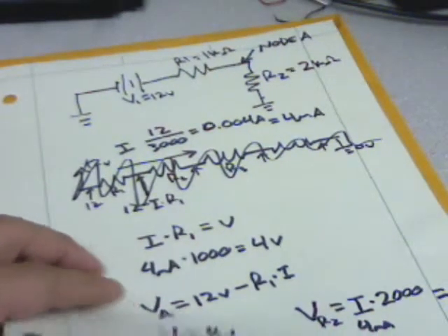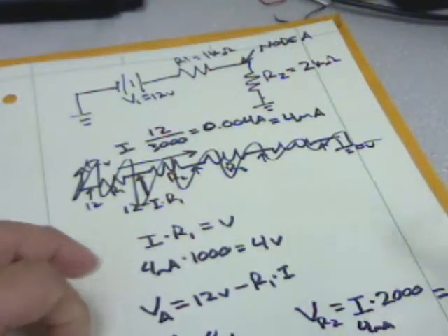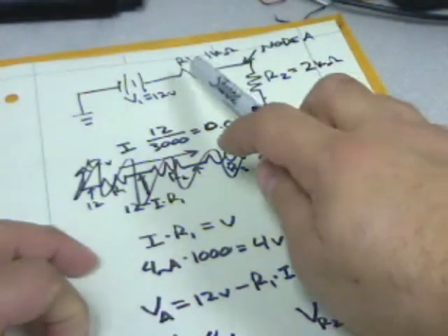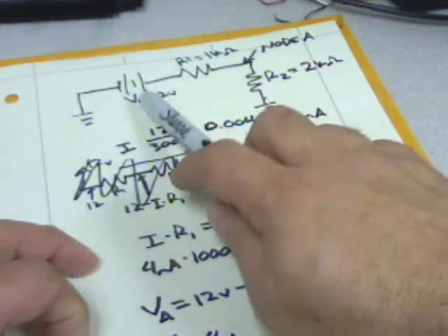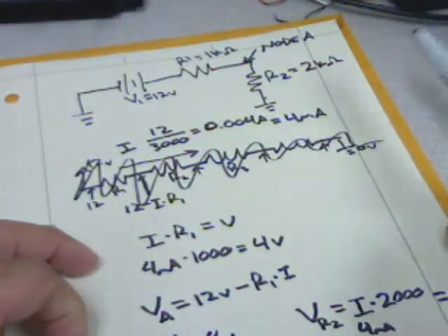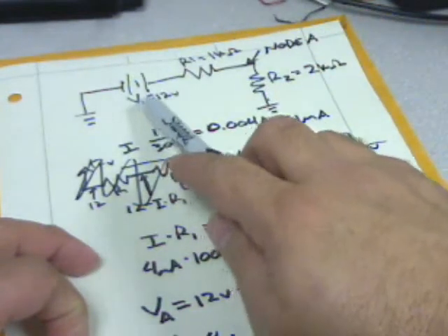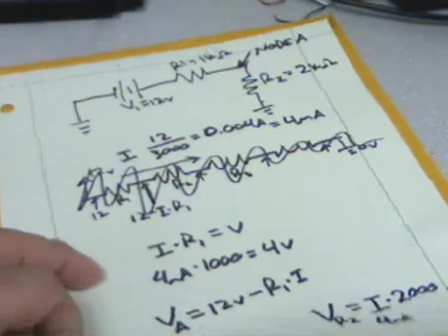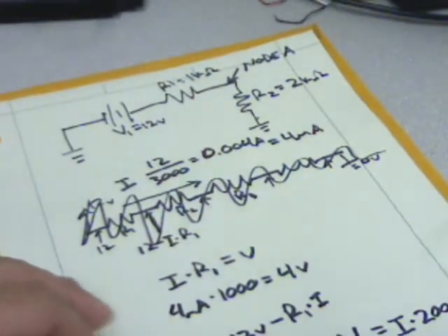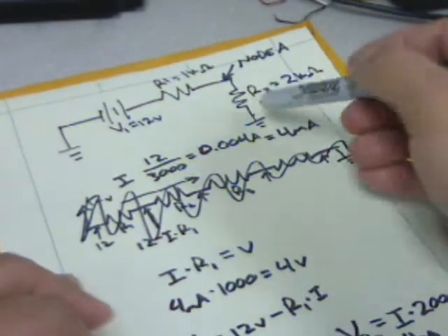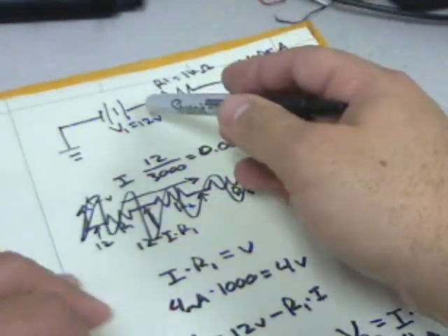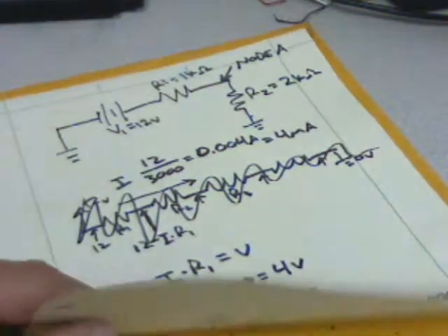That voltage drop is what we just talked about. And in fact, if we look at this, you can see that the voltage drops equal the source voltage, and that's basically Kirchhoff's voltage law. Because there's 4 volts here, 8 volts dropped here, that equals 12 volts, and that's how much voltage there actually was, and so that's Kirchhoff's voltage law. It's intuitive and makes sense, and so we should be able to understand that to get back to 0 volts, starting at 12, we had to lose all 12 of those volts.